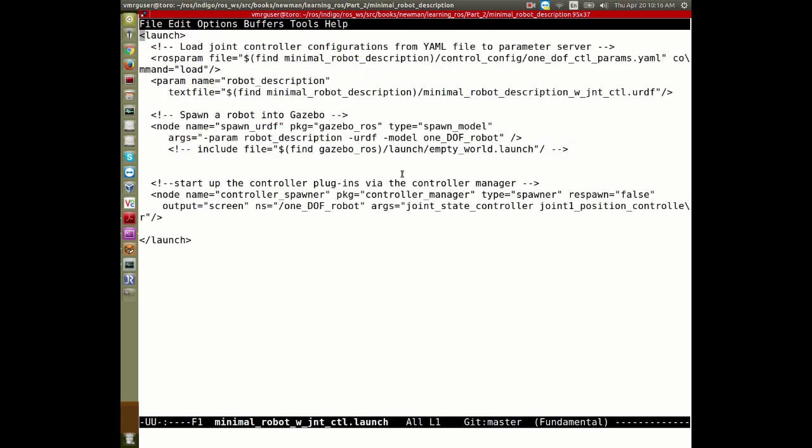And then you need to pass those as controller names. Sometimes we will have position controllers, velocity controllers, effort controllers. And sometimes you'll have them for each joint. So Baxter has 7, right? So you need to put a list of 7 controllers, maybe plus the joint state. Yeah? This list can get very long. You can compare this to Baxter files for those of you that have some experience to see how this looks for a more complicated robot.